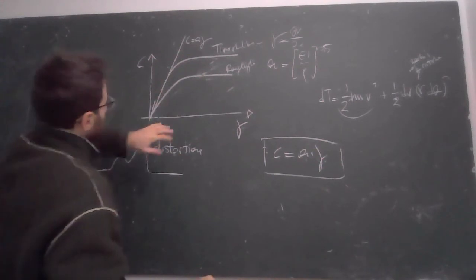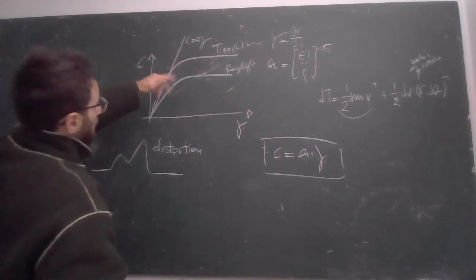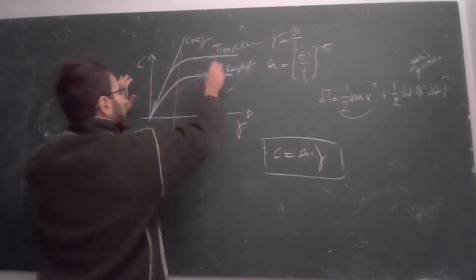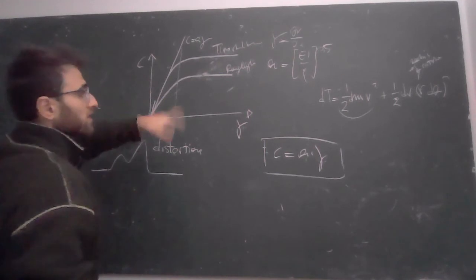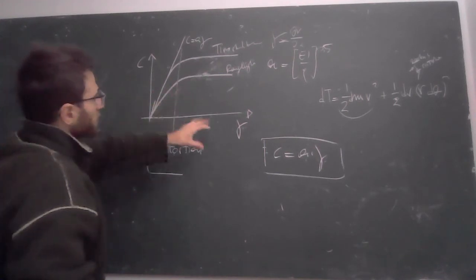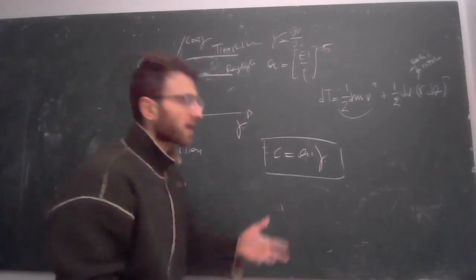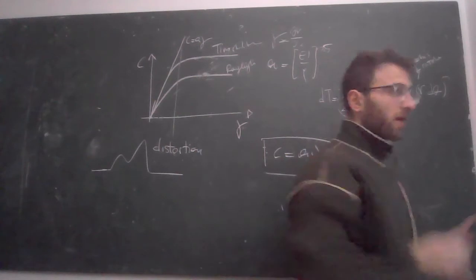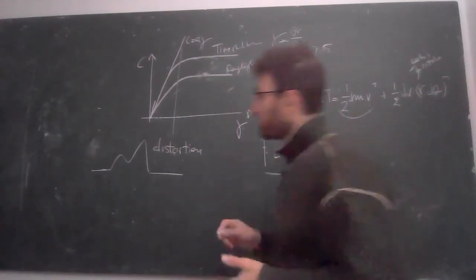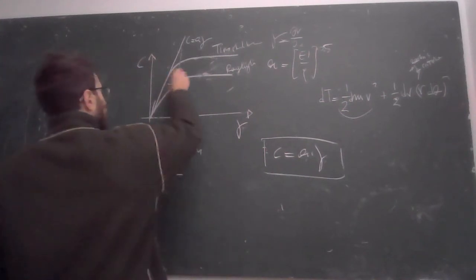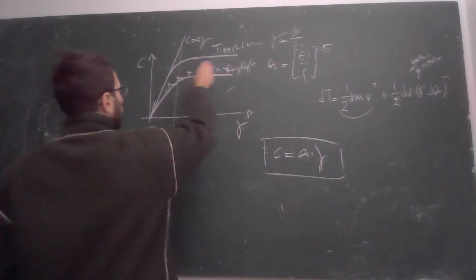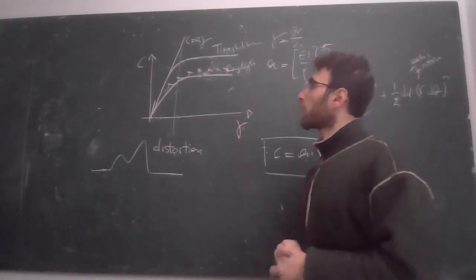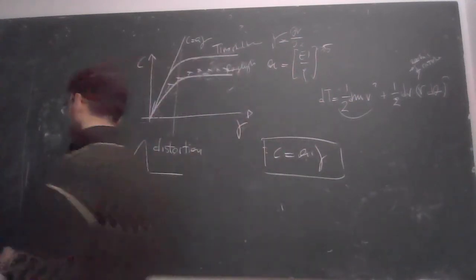So it is not true that as the wave number grows, the velocity tends to infinity, but after a certain wave number, the velocity is constant. It depends on the elastic properties of the beam, but it remains constant. The propagation, the information, the pulse cannot go with a higher velocity than this one. In fact, the experimental points are like this one. If we had to put some dots corresponding to experiments in that graph. So that's how things happen in reality.